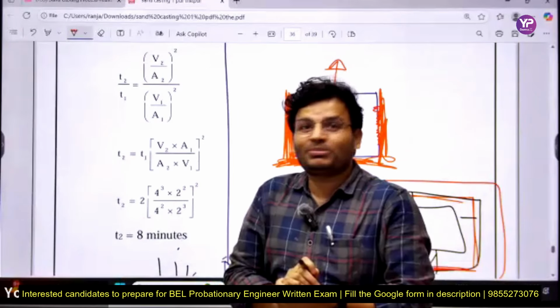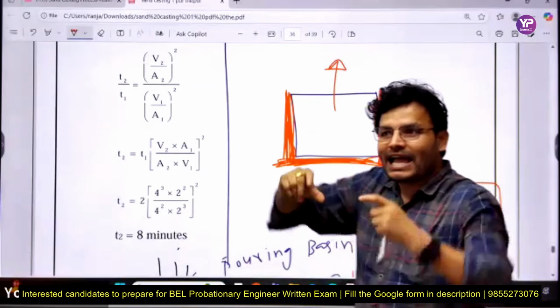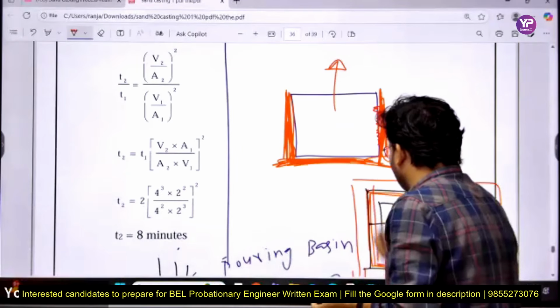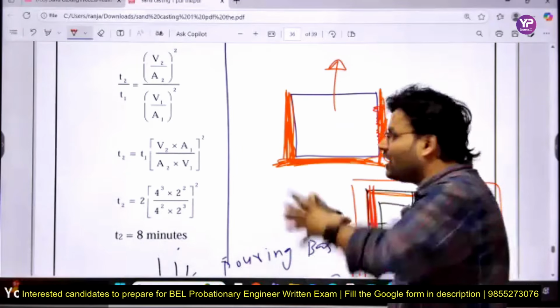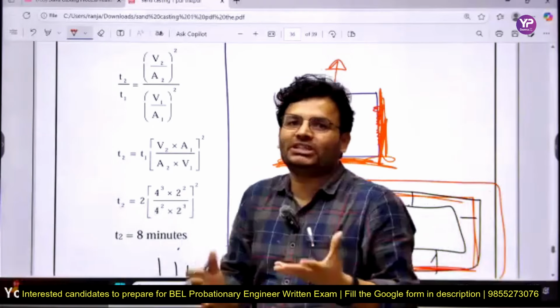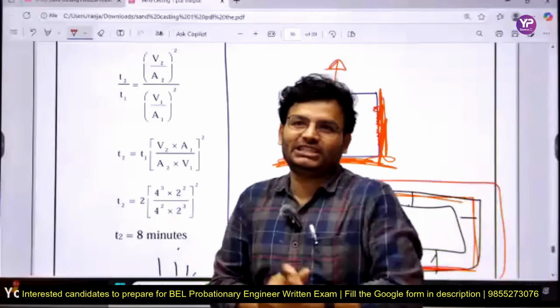Yes, sir. If I do the machining, some dimension will change. So already I have to give it as the last step. Suppose I have to cut from that one. So already I will give the larger size of the pattern, so that at the end I can do the machining and I will get the required shape, whatever I require. So this is called machining allowance.